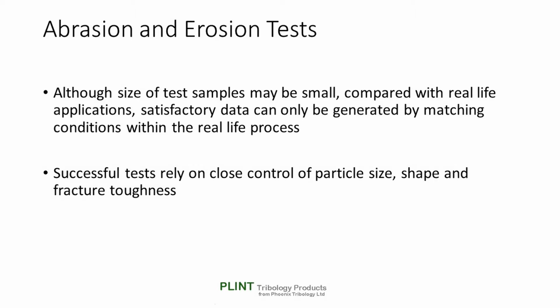In abrasive and erosive wear testing, although the size of test samples may be small compared with real-life applications, satisfactory data can only be generated by matching conditions within the real-life process. Hence, these are effectively real-life and not scale model test devices. It is not possible to extrapolate wear response from one type and size of particle to another. Tests rely on close control of particle size, shape, hardness, and fracture toughness, and this can only be achieved by careful sourcing and grading of particles.